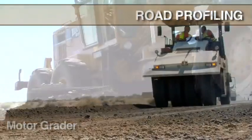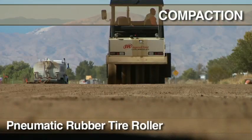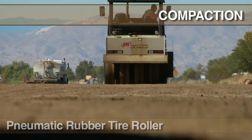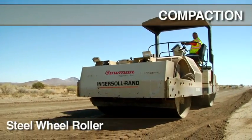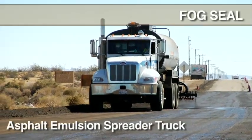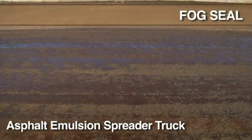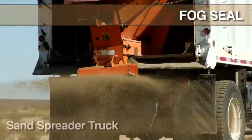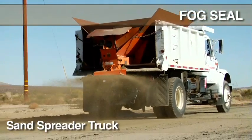After the road has been profiled, a 20-ton pneumatic rubber tire roller will then roll the material until a maximum density for this roller is achieved. Then a steel wheel double drum roller will finish rolling the material. An asphalt emulsion fog seal is then applied on areas that need to return to traffic in order to mitigate dust prior to the finished surface application. A sand blotter is often applied following the fog seal to prevent tracking.